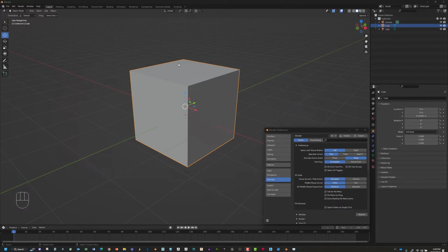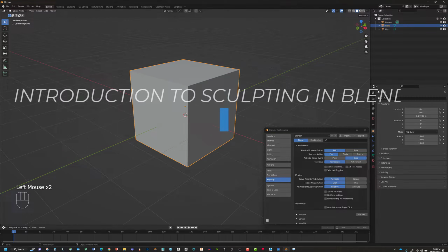So one last thing that I wanted to note is whenever you're in the Blender key mapping, if you have it on the translation, rotation, or scale gizmo, or this universal gizmo tool that you have here, if you want to go to the pick tool, the hotkey for that is if you tap W, and it'll go to the pick tool. Now if you tap W multiple times, it's going to cycle through different types of pick modes, and you can explore that, but the only thing that I'm really concerned about is just this selection type that you see here for selection of a box.